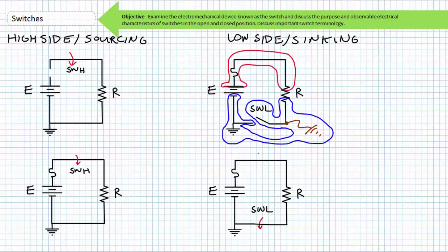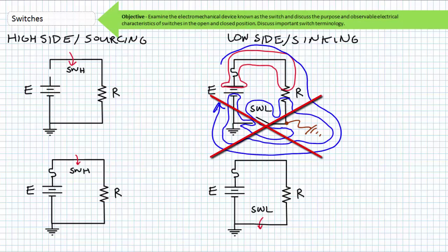In this case, the electrical load could unexpectedly energize. And here's what's scary: without the operator closing the switch. The switch is essentially bypassed by this errant wire connected to ground. Because of the pooled ground arrangement, there exists a return path to the source. In this case, the fuse cannot detect or resolve this accidental short because current drawn by the electrical load is inside its operational range. An errant short inside low side switching arrangements can sometimes unexpectedly energize the electrical load, often